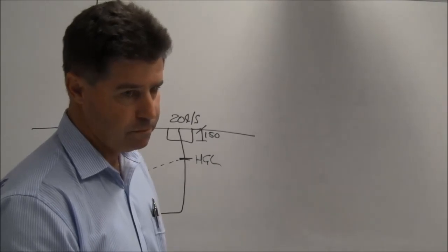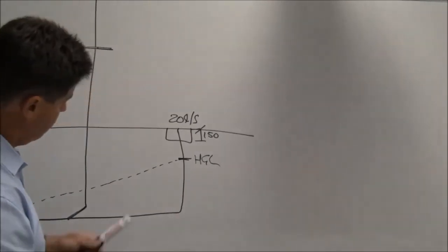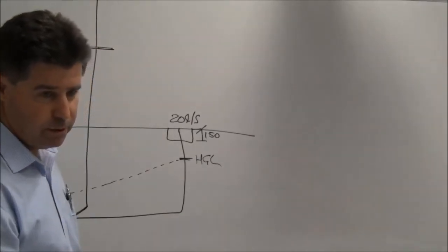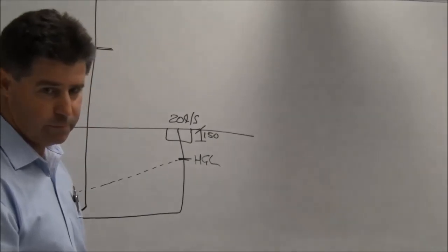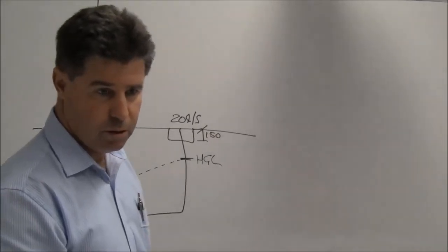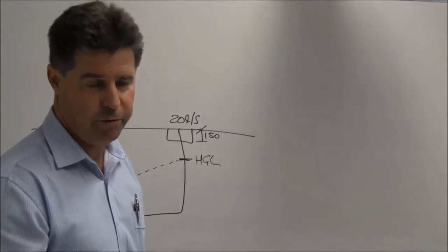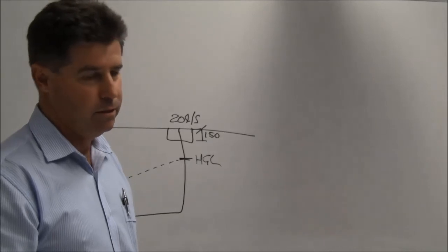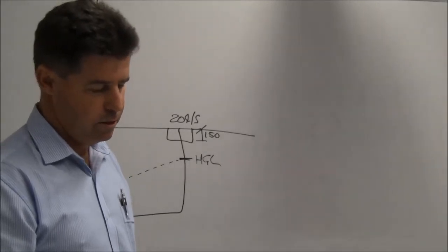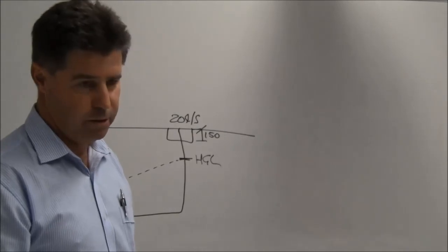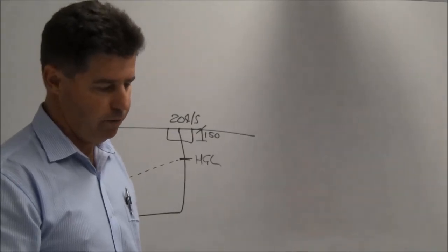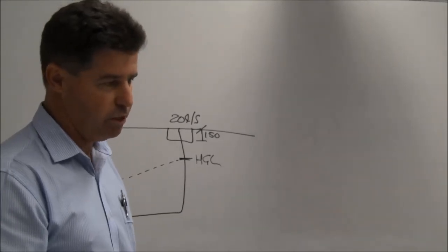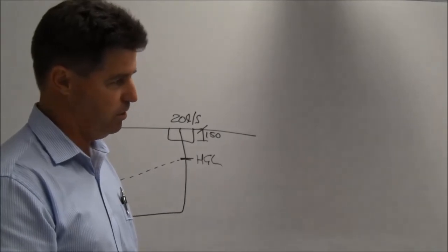So if that slope went above your pit and it's going to overflow, you can increase the size of your pipe. That's correct, that's one solution. Increasing the size of the pipe is one solution, yes. Or would you increase the grade? You could do both. You could increase the grade if you've got the grade to play with. Increasing the grade with smaller pipes obviously introduces more friction. So believe it or not, the friction head actually increases.